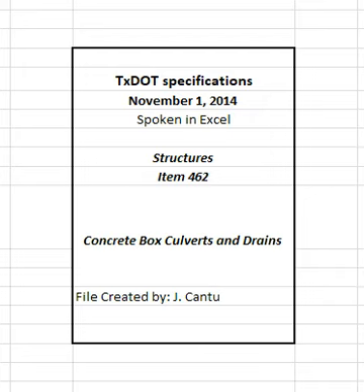2.5 Marking. Mark precast boxes with the following: name or trademark of fabricator and plant location, ASTM designation, date of manufacture, box size, minimum and maximum fill heights, designated fabricator's approval stamp, boxes to be used for jacking and boring, when applicable. Designation SR for boxes meeting sulfate-resistant concrete plan requirements, when applicable, and match marks for proper installation, when required under Section